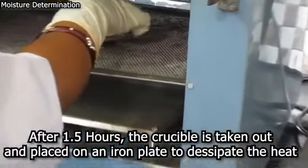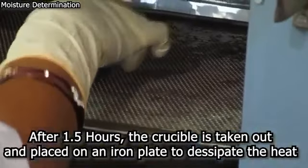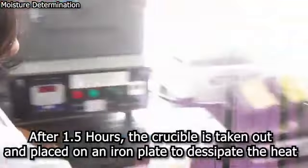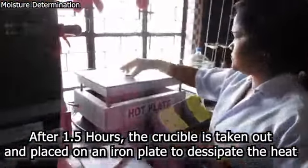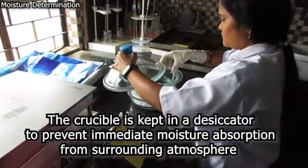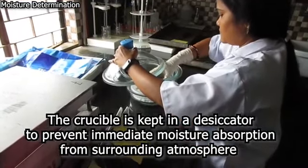Thereafter the vessel with cover or lid is brought from the hot air oven and kept in a desiccator for 20 minutes and then weighed and percentage of moisture is determined. If the sample is not put in a desiccator, then it might absorb moisture immediately from the surrounding atmosphere.